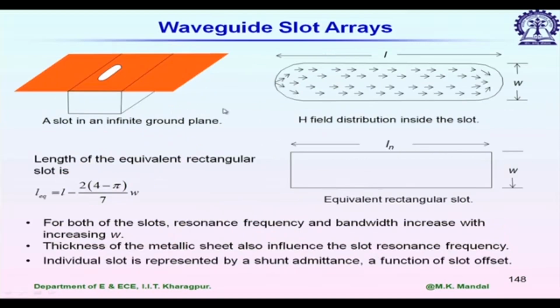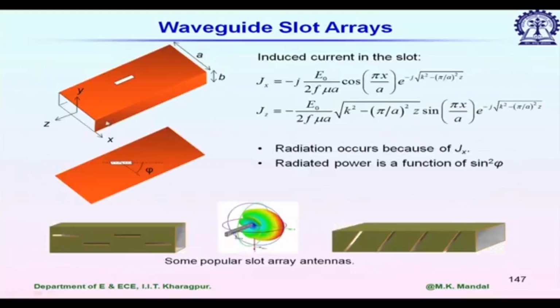Now, at millimeter wave frequencies, fabrication of the slot is a problem. Why? Its dimension becomes very small. Then how to drill a slot in a brass plate? Usually it is done by laser drilling, and we can control the cross section of the laser beam. The problem we face with laser drilling is that we can't obtain the sharp corners, you can see the rectangular shape of the slot. So, we have a sharp corner here, we can't fabricate that structure.